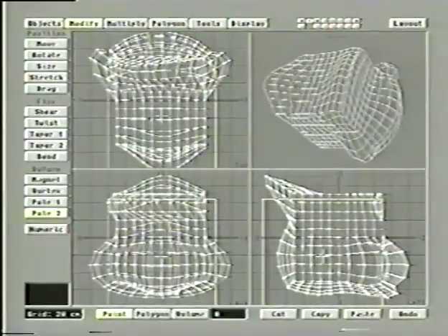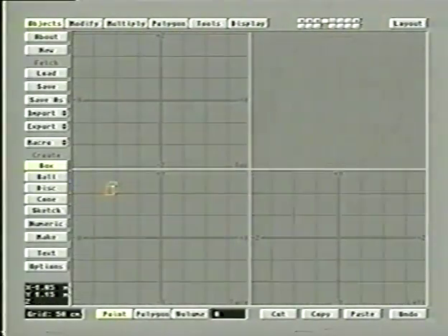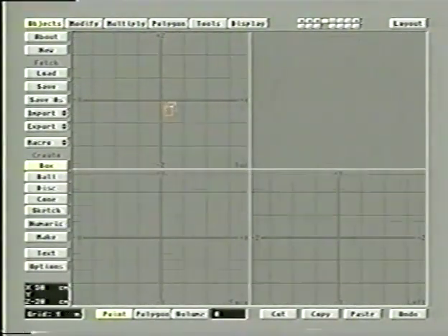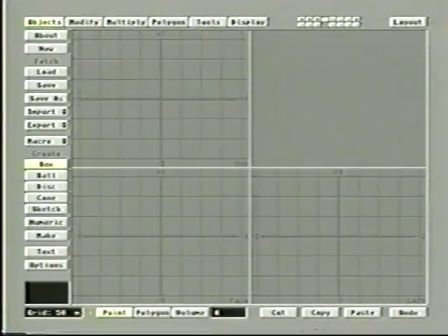So we'll start with magnet. The idea behind creating terrain is we use the magnet tool. So let's see how this works. We're going to go to an empty layer, and we're going to drag out a box, and we'll make it a perfectly flat box. So I'm going to the top view, and I'm using the comma key to back off till my grid is fairly large.